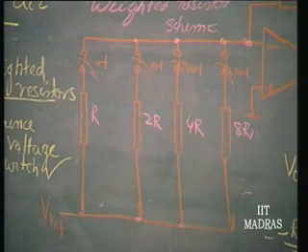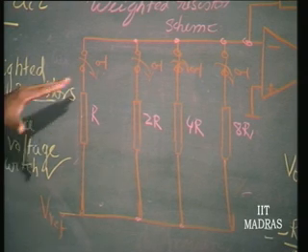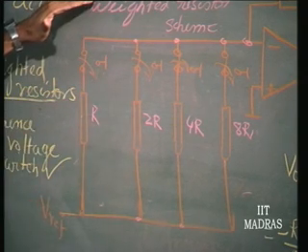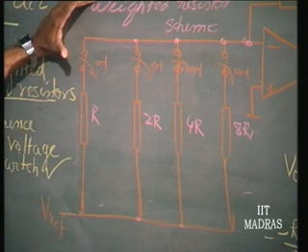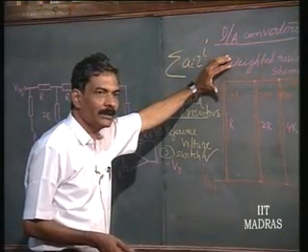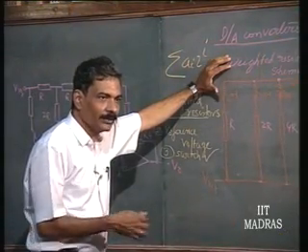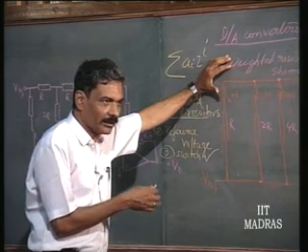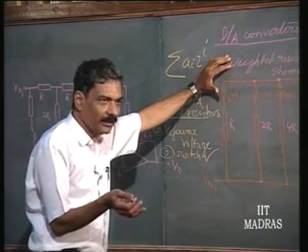So, this is what is called current switching, and it is this current switching which is now responsible for the increased speed. So, you can see here the subtle difference between location of the switch resulting in improved speed of operation. The price you are paying, of course, is in terms of the number of switch electronic components. That does not matter in an IC.